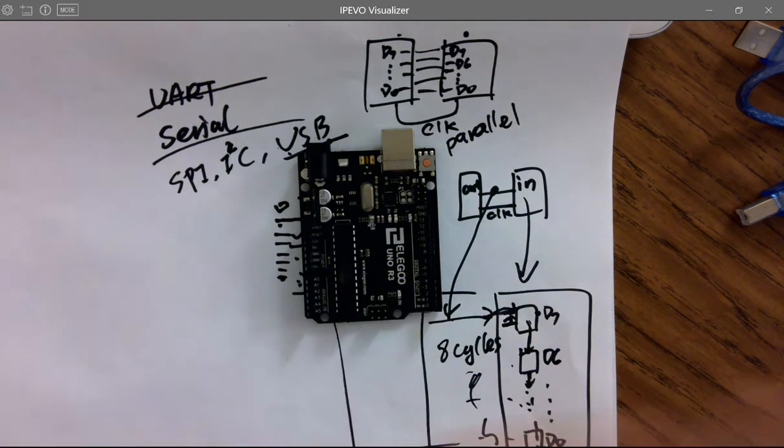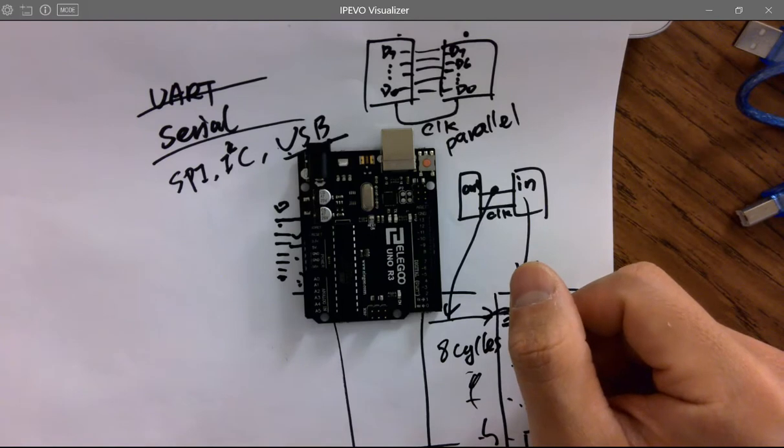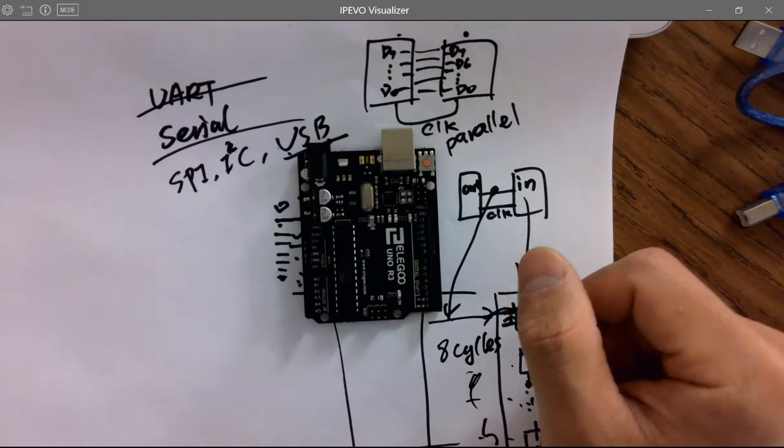Usually the newest technologies like 20 nanometer, 25, 22 are used for digital designs, which is fine, but for analog, you just cannot use such small transistors. I think 65 probably is the smallest you can use for op-amps.